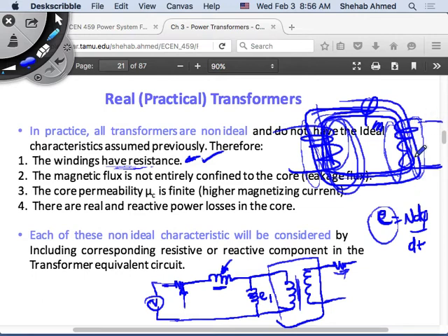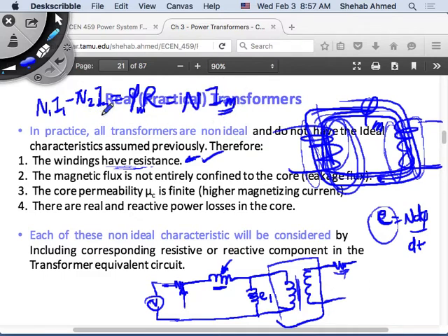Before you connect the load, no current is flowing. After you connect the load, current starts flowing, and then flux will be generated due to this winding as well, and you will have flux that is helping create the magnetic field, the mutual flux. This N1 I1 minus N2 I2 quantity is equal to some phi times the reluctance, which is equal to some N times the magnetizing current. This I1 minus I2 is equal to the magnetizing current. So some of it is creating that, and then some of it is just flux that is flowing in the air.